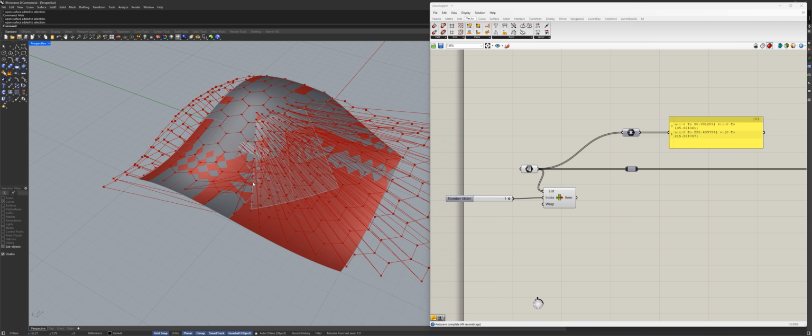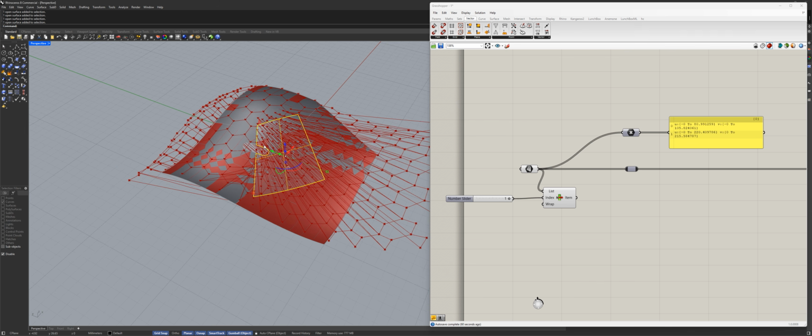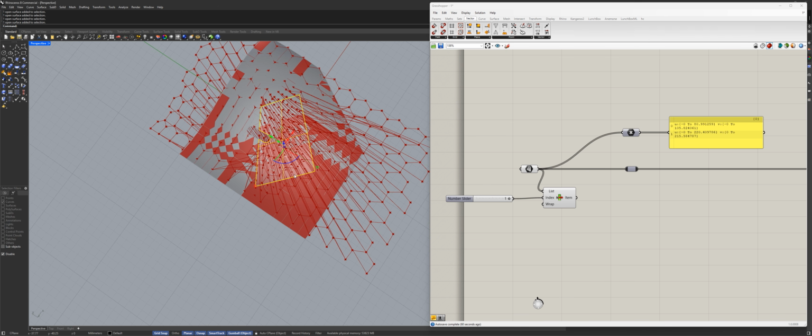So the question you might have, okay, can we actually take this construction and basically assign a single domain, the domain which will be true for this surface and for this surface at the same time, right? One big uniform parametric space, because once again, with two different parametric spaces, it goes through one, then it goes through the other one, it goes in different directions, everything is breaking. Well, the quick answer for that, no, we can't. This is the nature of NURBS.